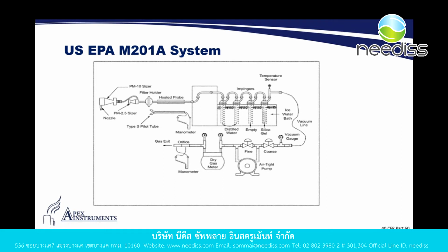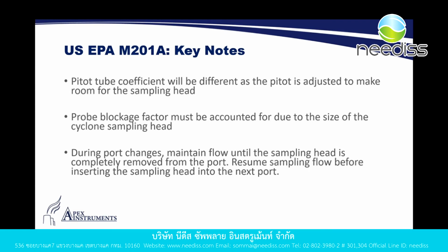I highly recommend doing that for all methods. It could save a lot of effort and a lot of heartache getting silica gel into your gas meter, which gas meters do not like silica gel. So just a little stack testing tip.